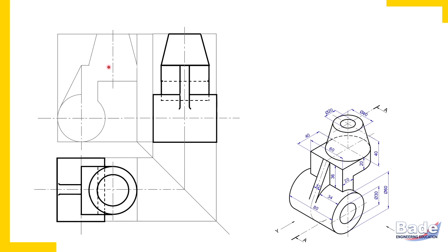So that is why we should erase this boundary and we should erase this boundary. Actually, this rib here is also getting cut. Check here that cutting plane AA, this is how it makes exact two halves of this object. So this rib also is getting cut. When you imagine a cutting plane line here, watch here.